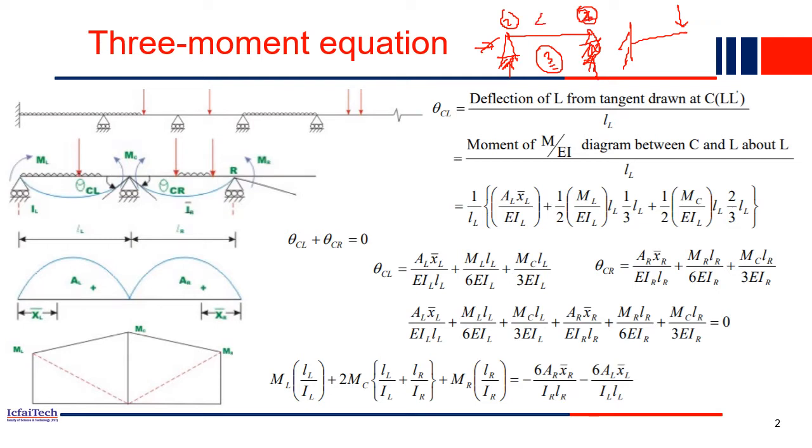So in total you now have four unknowns, and you have three equilibrium equations, right? So using the equilibrium equations we can calculate at most three unknowns, but still one more unknown we have to compute, right? So using the normal method we can't solve indeterminate structures. So this beam, if this end is hinge and this end is also hinge, then we call it an indeterminate beam of degree of indeterminacy 1, because three unknowns we can calculate but one unknown we cannot calculate. So it is a degree 1 indeterminacy of this beam.